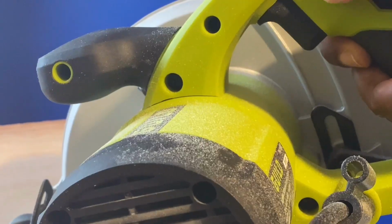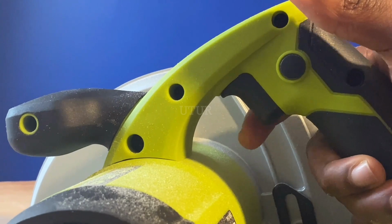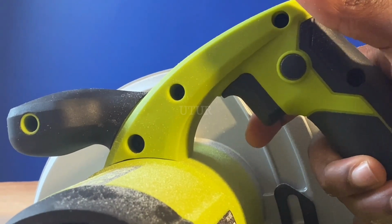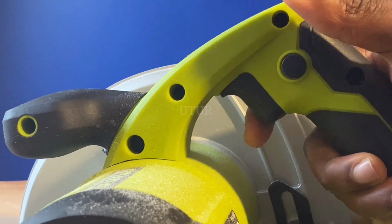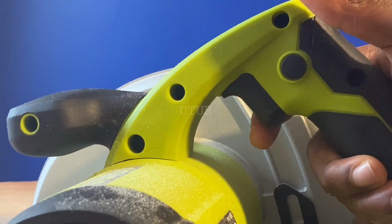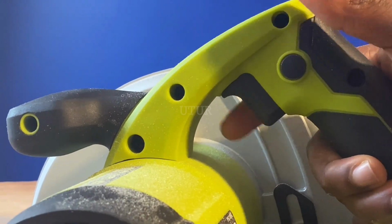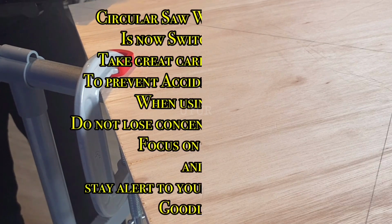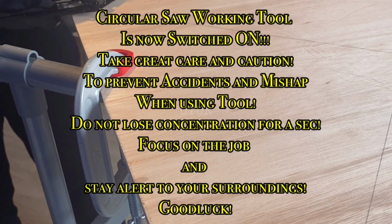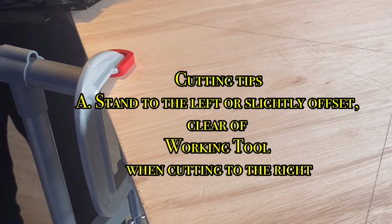Firstly, depress the lock off button and then subsequently depress the on and off switch. After depressing the on and off switch, release your hands from the lock off button. The switch is now on from here onwards. To switch off, just release your hands from the on and off switch. The blade may continue to rotate after switching off, so just wait until the tool comes to a complete stop before setting down the work tool.